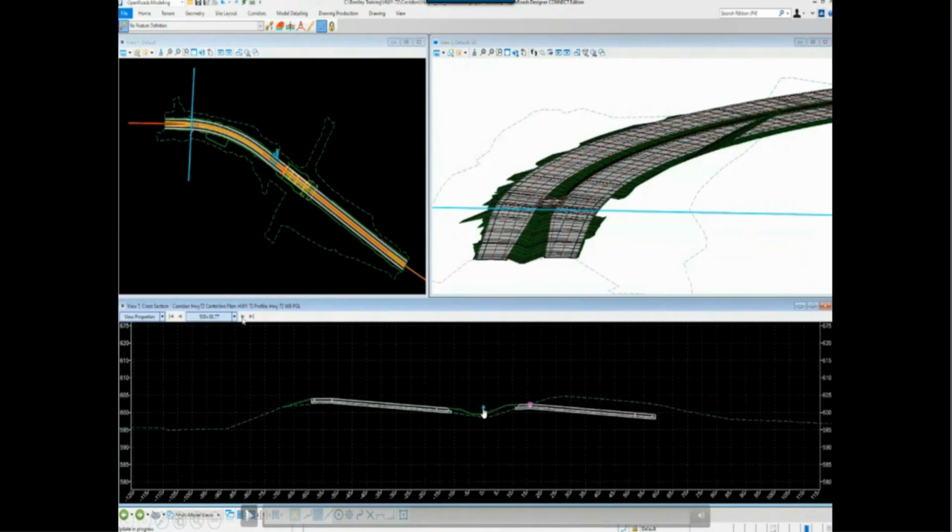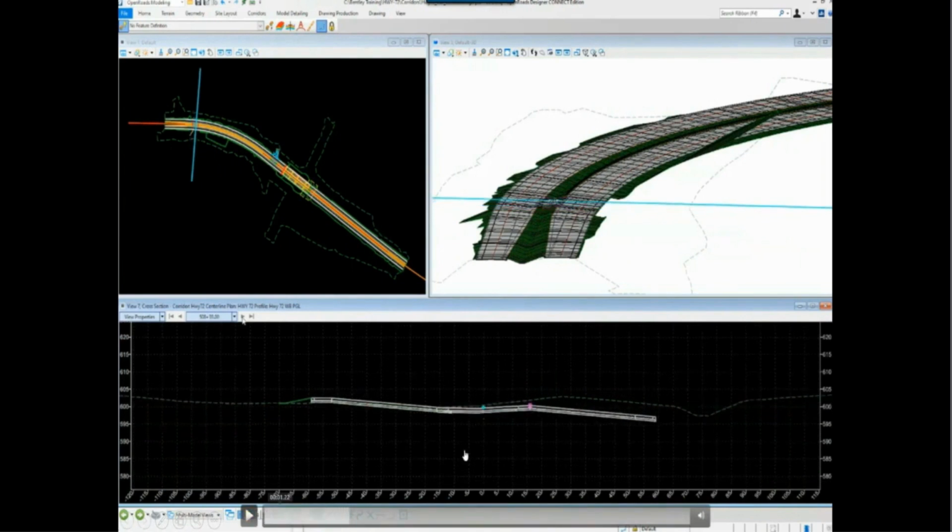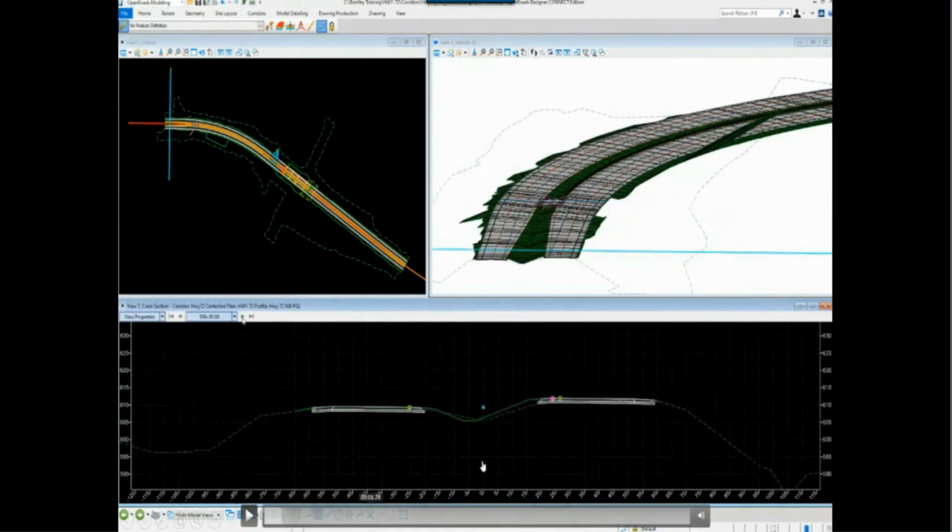So as we widen to the middle, if you'll notice the existing roadway is quite a bit higher here. We want to be sure to maintain a more level elevation between the two roadways from left to right, okay? Now, if we go back to the beginning of the roadway, as we look into that transition, you'll notice, again, we're going to have to modify the vertical between the eastbound and the westbound sides of the roadway. So we'll have to, again, create that control line vertically.